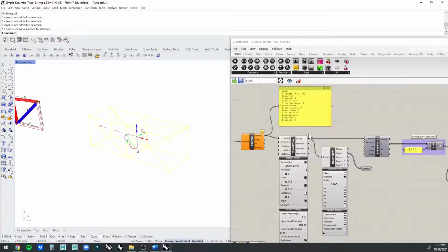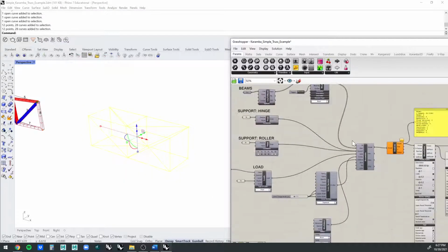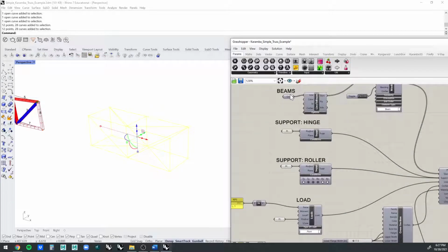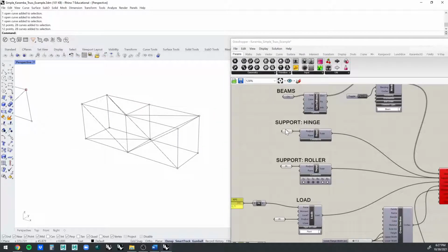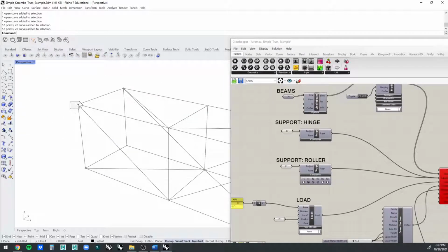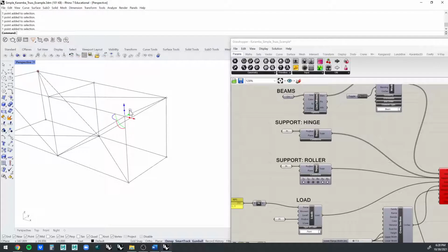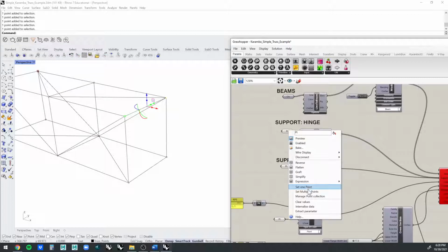All right, so let's move to a 3D example. Mostly going to be the same. I'm going to right-click all of these things and then set multiple curves. That changes over here, but now things are not working. I have to select 2 points on this side. I'm holding down Shift, selecting both of those points, right-clicking and setting multiple points, setting those to be my hinges.